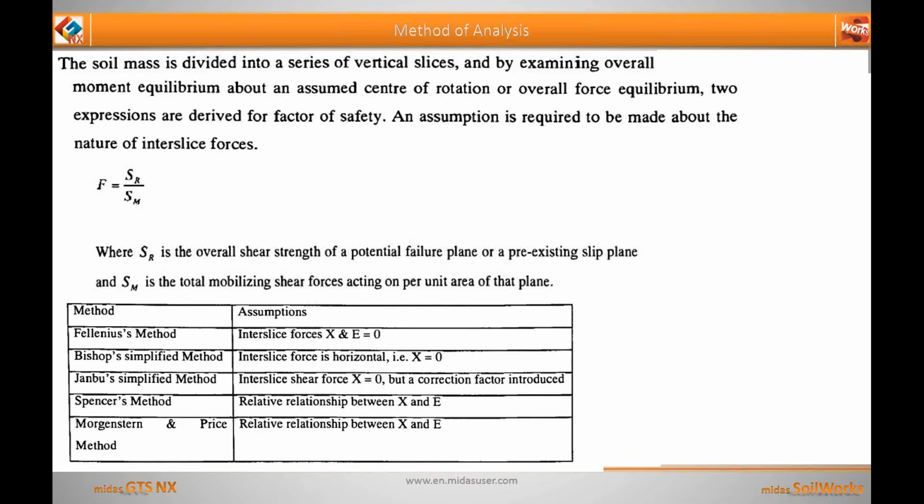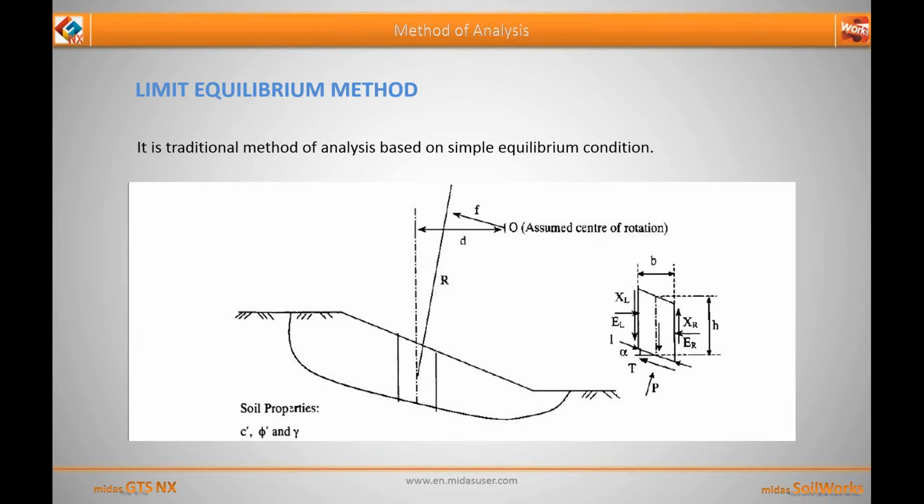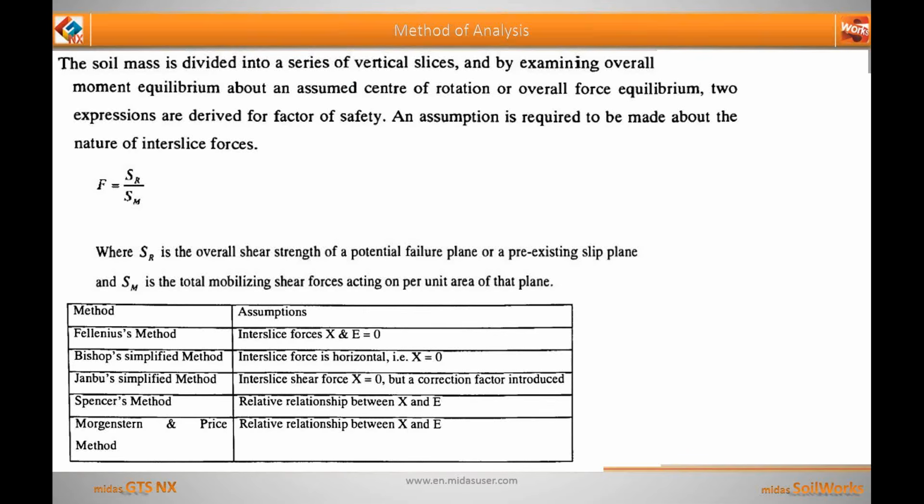Now if you look at that particular slice, you will see that there are a lot of forces: the self weight, the interslice forces, and similarly the normal reaction from the bottom. To consider the equilibrium condition with all the forces, the equation becomes indeterminate in nature. So to make it determinate, a few assumptions need to be made, and this gives rise to the various methods.